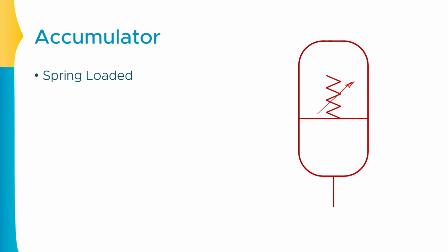The third accumulator is the gas charged accumulator. So on the upward side, we will have the arrow of the pneumatic representation. This specific arrow represents the pneumatic symbol. As you can observe, if it is completely filled, it will represent the hydraulic symbol, but over here this represents the gas in this case. So this symbol is the gas charged accumulator symbol.